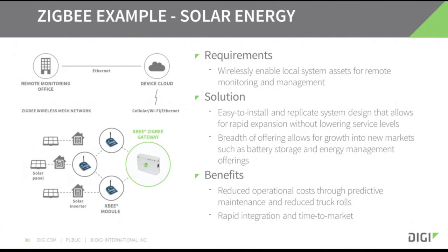Another reason ZIGBEE was great for this application was because cloud connectivity was required. And a gateway operating as a coordinator on this network, actually inside of the home, connected to their internet connection, provided that function, connected those wireless ZIGBEE networked devices to a cloud-based application and allowed our customers to understand the energy production and consumption data being generated by the system, as well as provided them with the capability to upgrade their firmware over the air from the cloud.